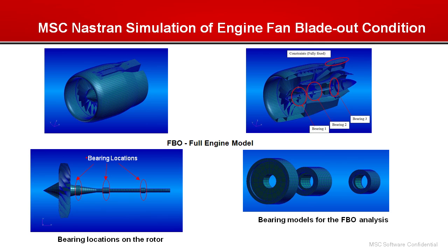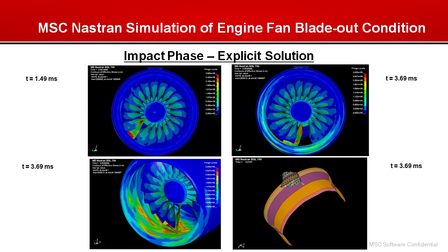The bearing models and their properties are important design considerations to simulate the fusing during the fan blade out and rotor dynamics analysis. Fusing is basically an event where a bearing or other support structure fails as a result of high loads beyond the design strength of the fusing structure. Basically, the stiffness drops to 0. To come up with the stiffness of these bearings, we had to do a trial and error to come up with the right stiffness as required in the design. So we were monitoring the force displacement characteristics.